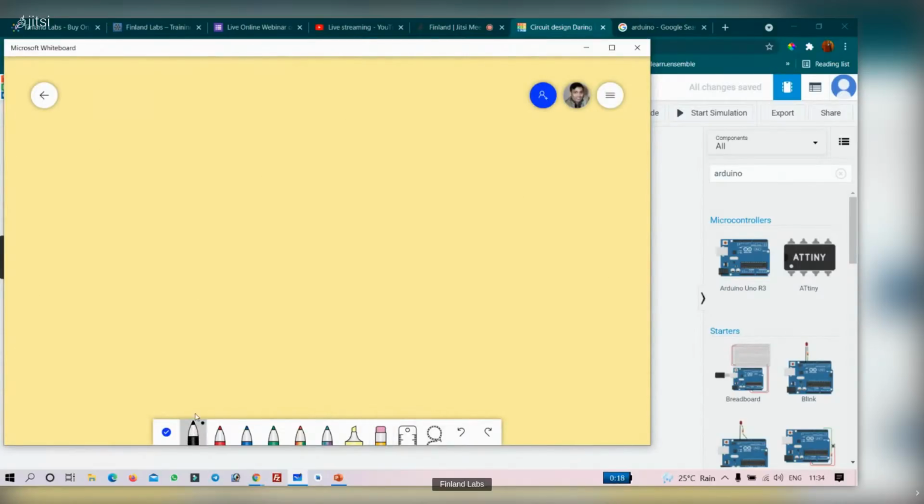Basically, see, this is the symbol of LED. This is your positive terminal. This is your negative terminal. So if I have to connect LED, I cannot directly connect to a battery. If I am having a 9-volt battery, let's suppose, I cannot connect because it will make that LED fuse. So we have to connect a resistor to that LED.